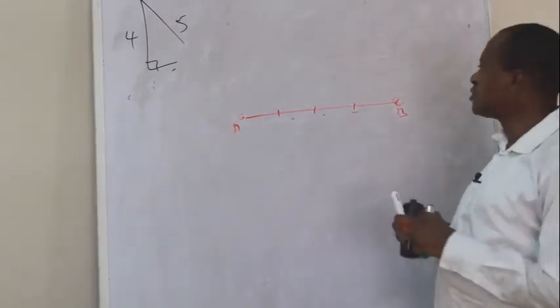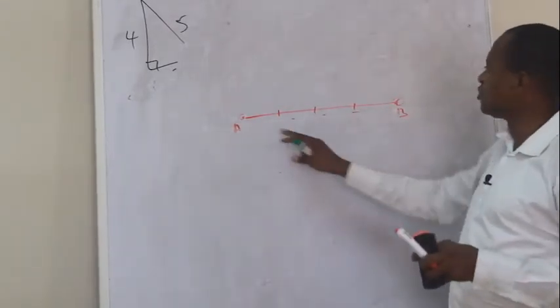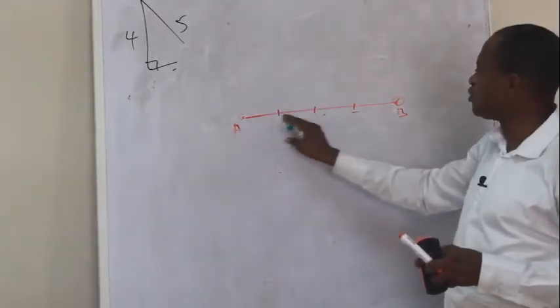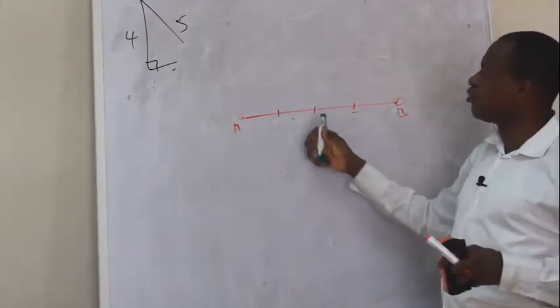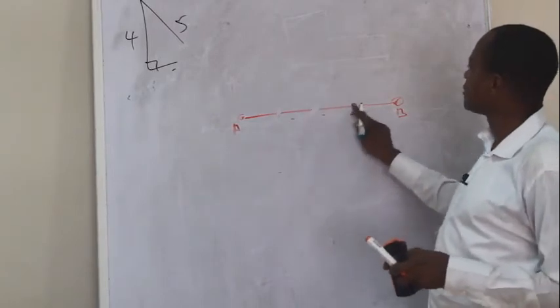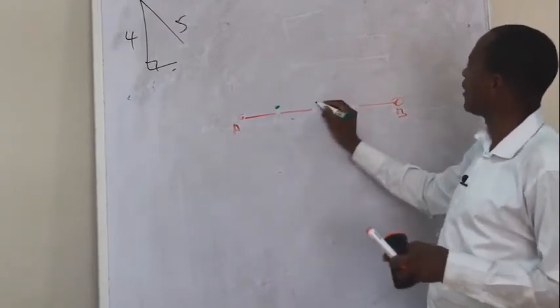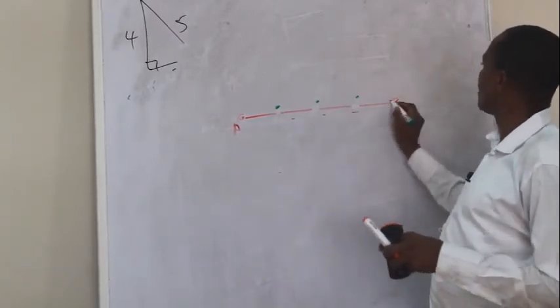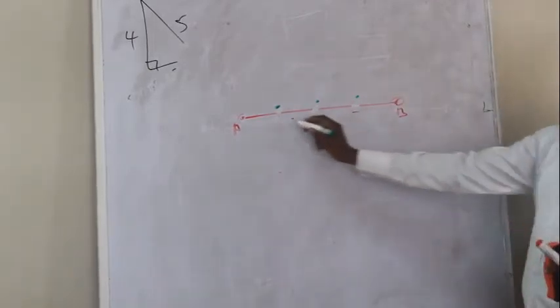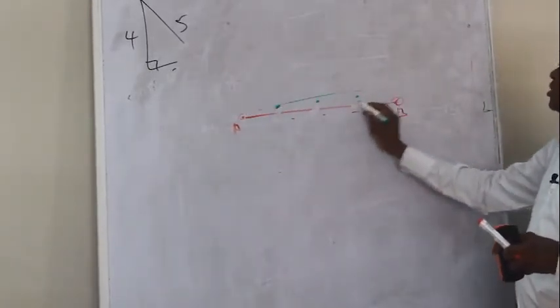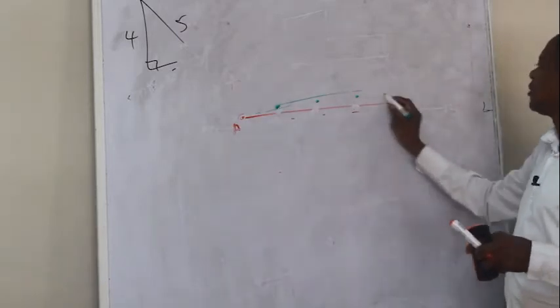But in a situation where the person who is ranging, who is to align points between here and here, does not do it very well, possibly the person puts the pole somewhere there, thinking that it's a straight line. This is a bad ranging. Later you come here.